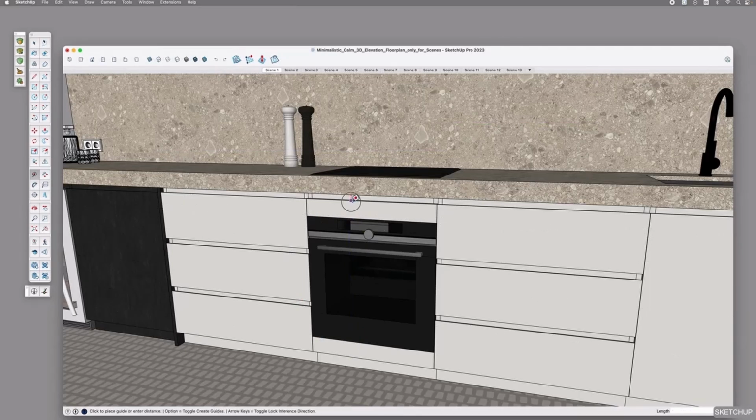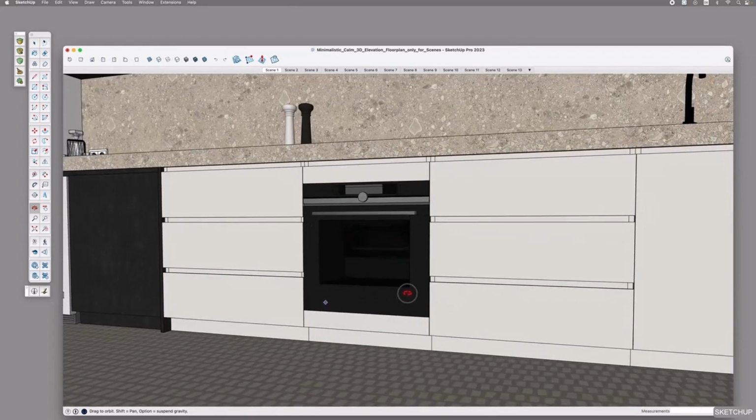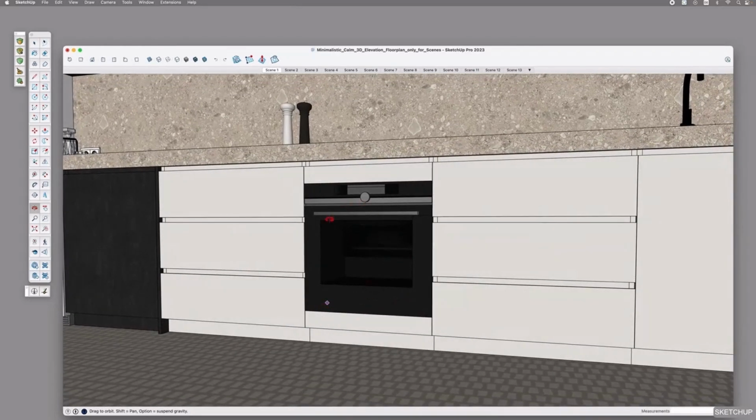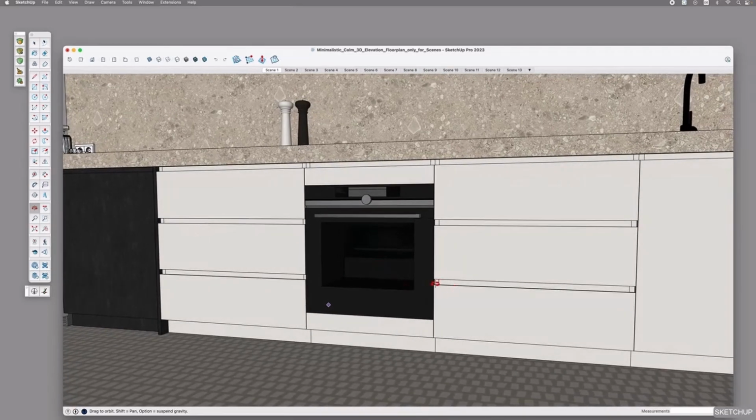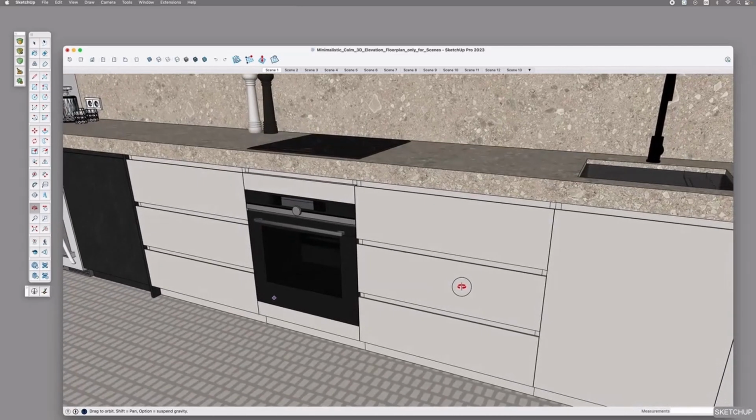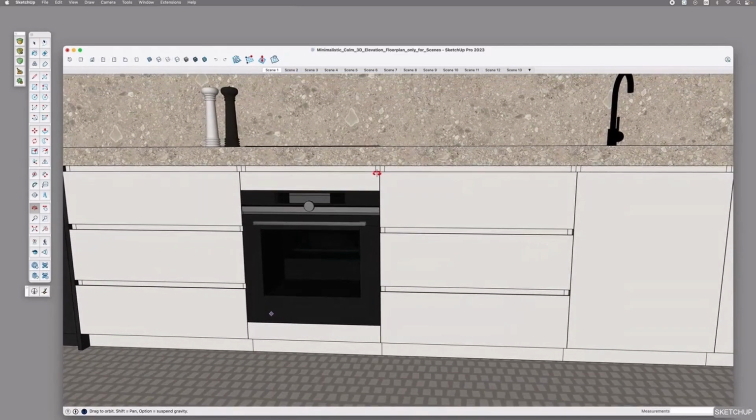If the total height allows, you can include blenders, filler pieces, or even a drawer at the bottom for added convenience. I can't possibly specify anything standard here, as this depends on the design of your cabinetry. Try to follow lines within the design, meaning if a close-by drawer bottom line is here, try to place the oven at the same line.